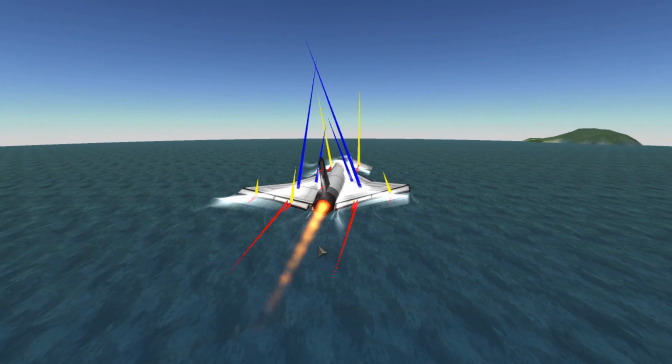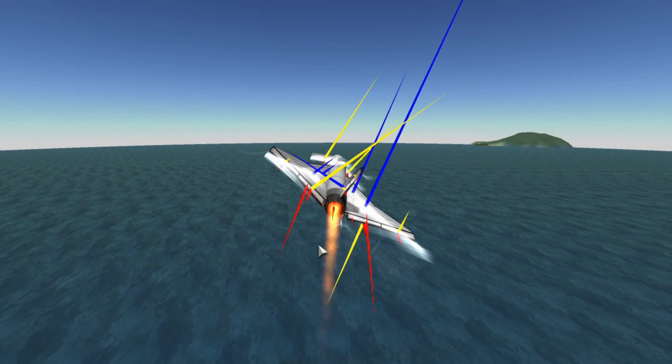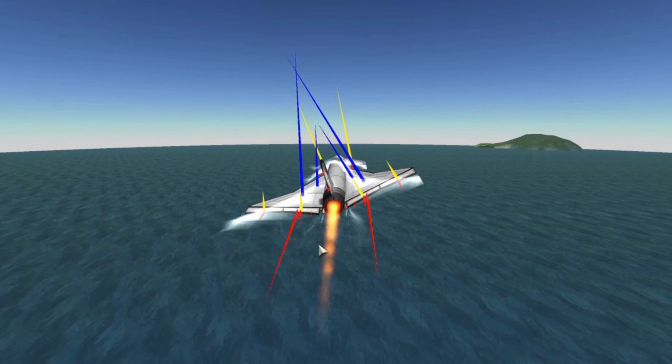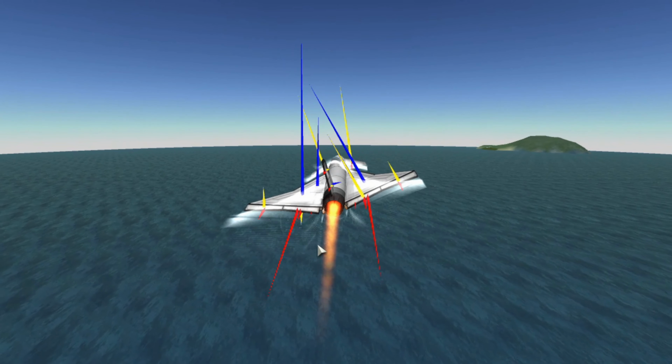However, dihedral wings will also make you experience less vertical lift because the lift produced by dihedral wings is not entirely vertical. It will make planes roll slightly slower because the wings will just try to counteract the roll.